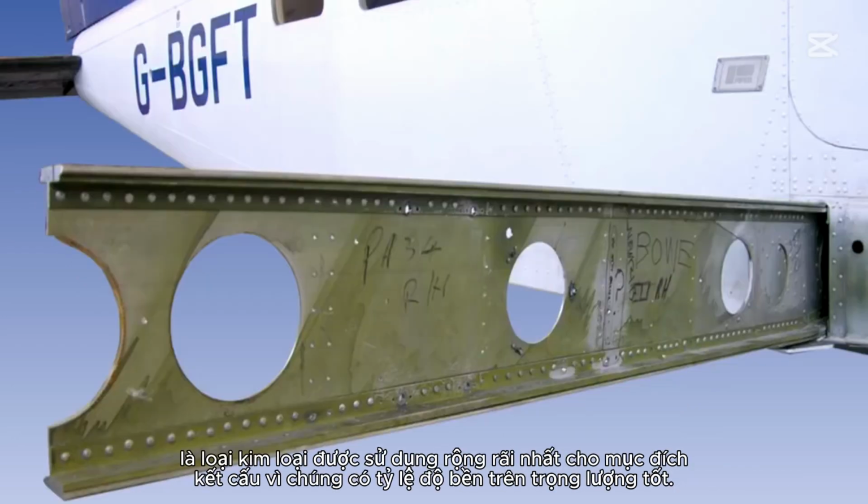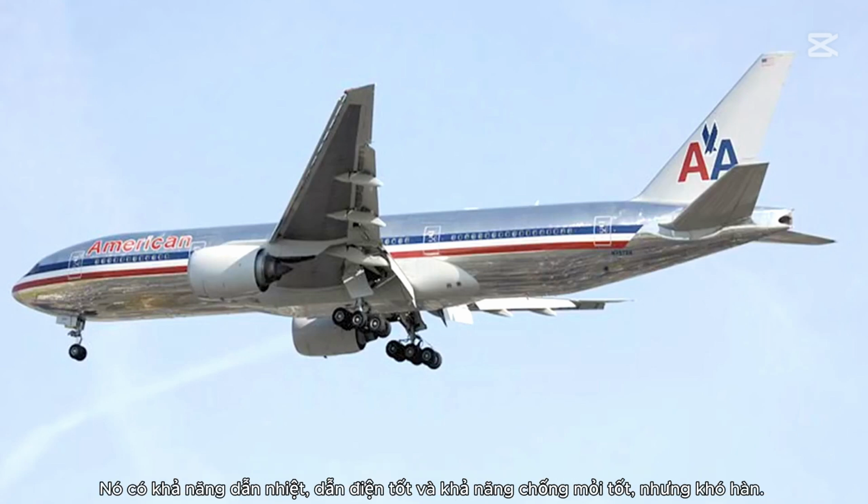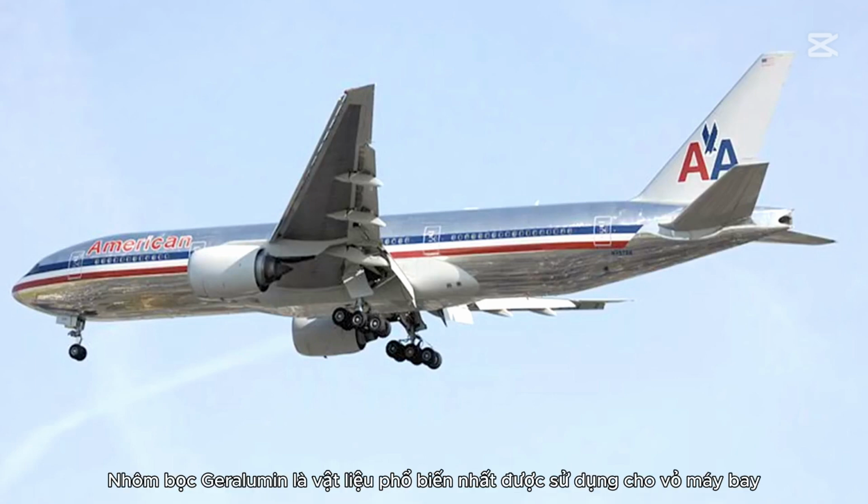Aluminium alloys are the most widely used metals for structural use due to them having a good strength to weight ratio. Duralumin is an aluminium and copper-based alloy which has poor corrosion resistance, except when clad with pure aluminium. It has good thermal and electrical conductivity, and good fatigue resistance, but it is difficult to weld. Aluminium-clad duralumin is the most popular material in use for airliner skins.